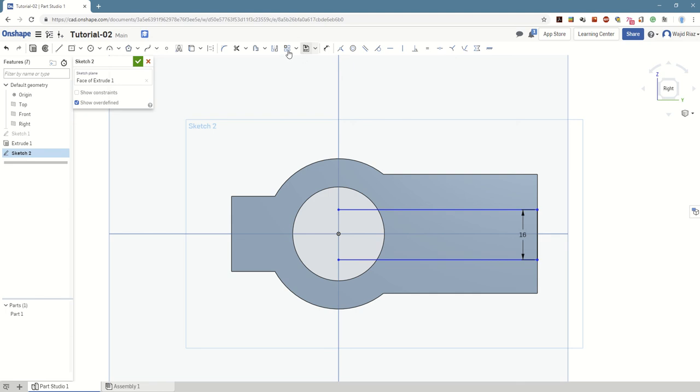What we need to do now is trim, or actually before that we need to make sure this is sitting in the center, so click either the top or the bottom, click that middle plane. Half of 16 is 8, shifts it to the middle. Now we're going to use the trim tool. Have you noticed that it's trimmed the whole aspect? Now whilst we might see a sketch or a line there, technically we haven't actually sketched there. So I'm going to press Ctrl Z.